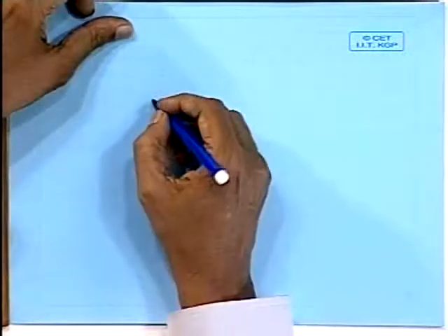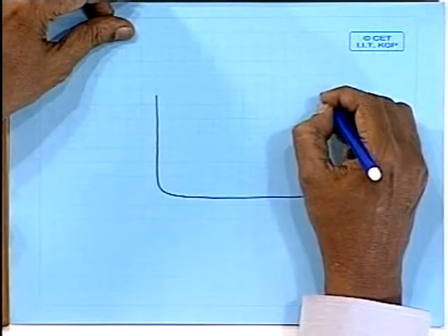Each structural component in a ship serves various roles with regard to structural loading, to withstand various load conditions. The primary longitudinal members, as you know, withstand longitudinal hull girder bending. But apart from that, shell plating also withstands hydrostatic pressure, perhaps I can explain it this way, that is coming due to hydrostatics in the transverse plane, hydrostatic loading in the transverse plane.